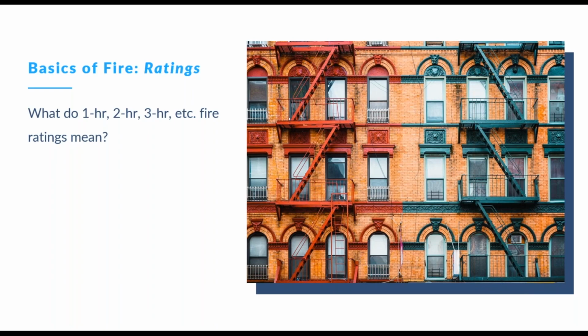And coming to PAC, the way it's been described to me is that it's not about making sure that the thing is fireproof, right? Like I hate the term soundproof, and it's also not that it's fireproof. It's just going to withstand fire for a certain amount of time to give people enough time to get out of the building, and also to give firefighters time to get in to help the people in the building that still need help. That's why for much taller buildings, we have higher fire rating requirements for egress passages, stairwells, and things like that, because it takes people longer to get out of those big buildings. So that's really what those mean.